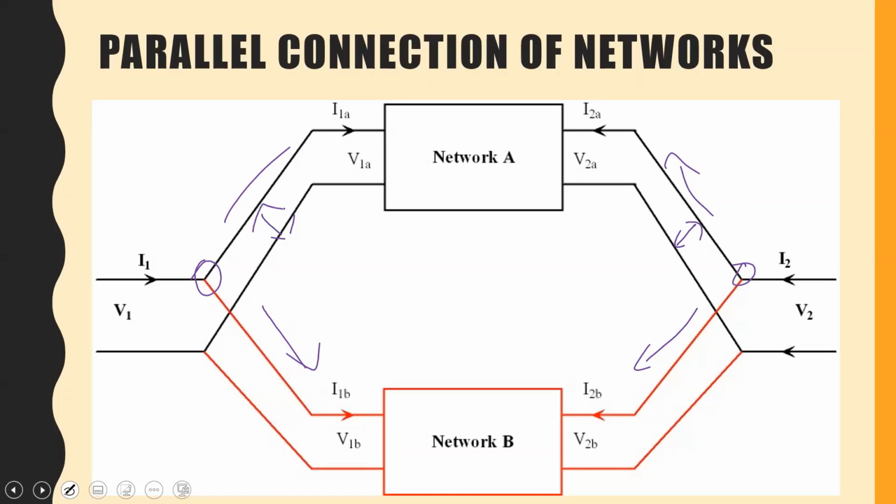So in essence, what we are saying is that these two networks are connected in parallel, based on what we know of parallel networks or parallel connected components. All right? So it comes back to some of the things I was emphasizing back in networks where I told you, you can look at just how the element is drawn, but you must always use the current reference to make certain determinations. So we see that these are in parallel. Is there anybody who is unsure about it?